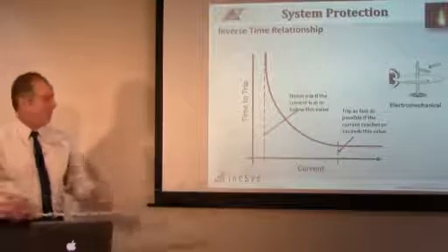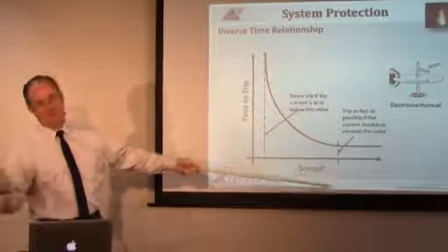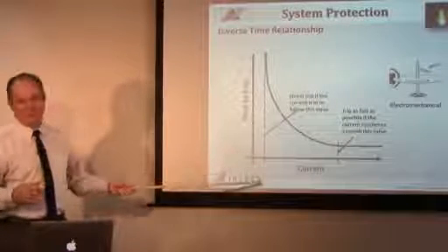The solid state relay says, all right, if I get a CT that's going to give me that current, trip. And my normal operating range is thus. So that's a difference with the solid state. And the solid state is so much smaller, so much more compact, so much easier. Plus you can have communication schemes where you can dial into the relay and check history. It records before the fault, after the fault. You get a snapshot of what actually went on in all three phases, all three currents, the voltages. Very informative type of relay when we deal with the solid state. That's why there are so many more solid state relays now than in the past, replacing the electromechanical relays.